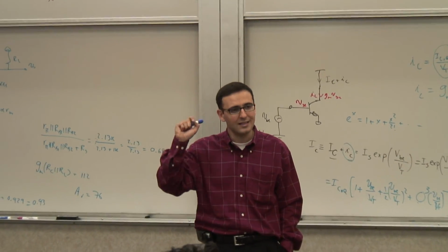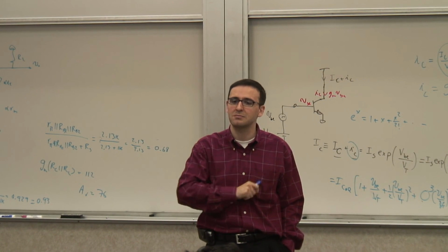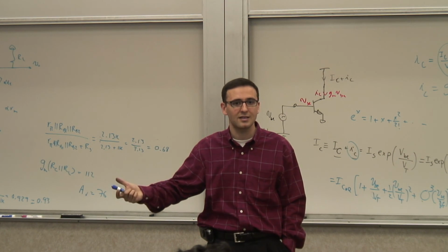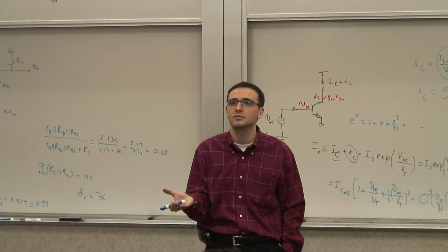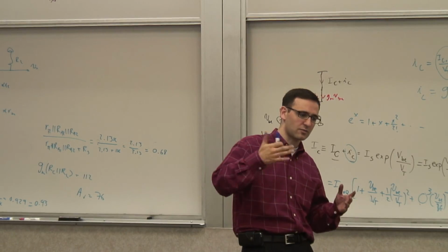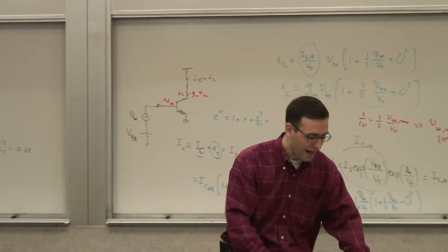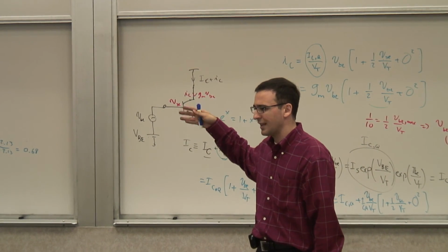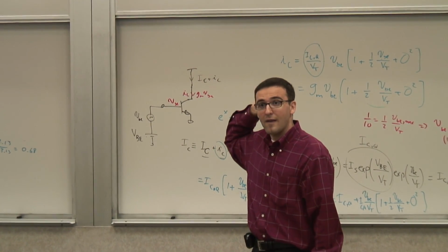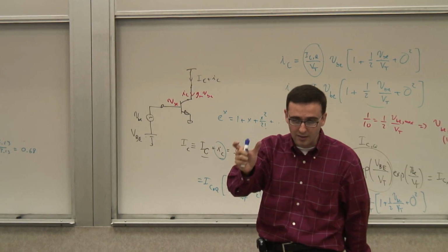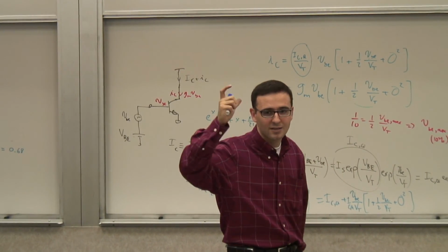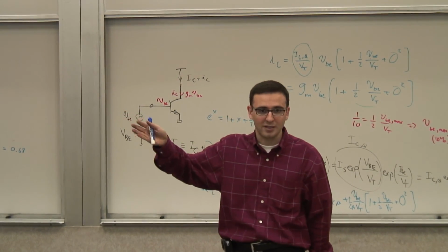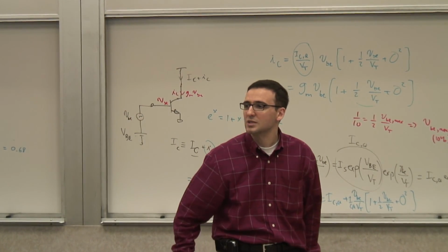You'll see in integrated circuit design, the mentality is that you can have as many transistors as you want. And when you use them, you will come up with different kinds of biasing techniques that are more suitable for integrated circuits. We'll see those next time: bias, current mirrors, and independent sources. And then eventually, at the end of the next session or the next lecture, we'll talk about truly the bias circuitry that's very independent of process, temperature, and supply variation. It's not zero dependence, but it's very low dependence. We'll see how those things can